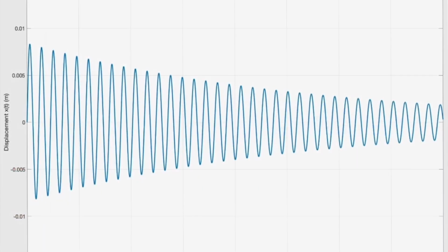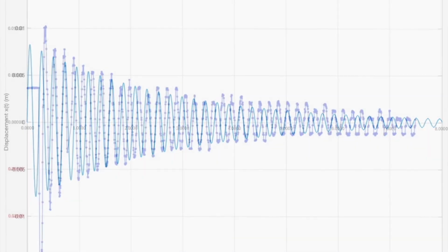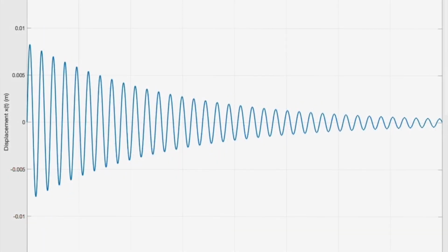Initially, the theoretical and experimental results did not match all that well. However, when we adjusted the assumed damping coefficient from 0.05 to 0.1, the two plots became very close. This highlights how sensitive vibrational systems are to damping and how hard it is to estimate sometimes.